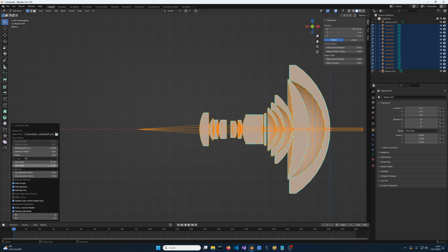And now if we're interested in displaying multiple angles at the same time, there is this field below the fan angle selector here, which is just labeled additional because the text is cut off, but that's short for additional angles. And here we can enter a list of decimal values separated by semicolon. So for this lens, for example, we could do 10 degrees, 20 degrees, and 35 degrees. And if I hit enter, then you can see we now get 4 beams in total.